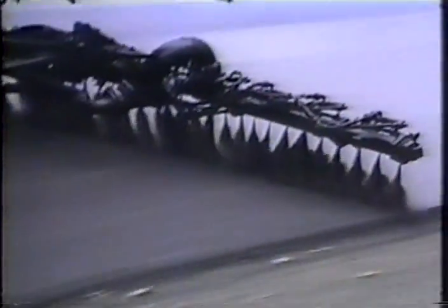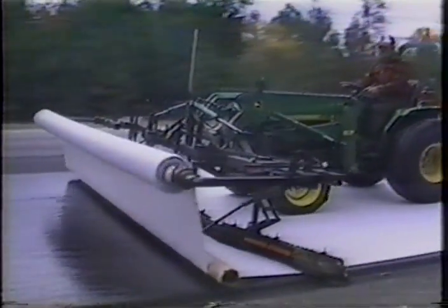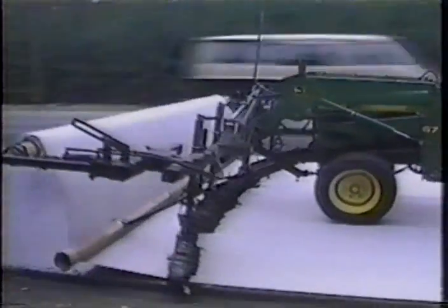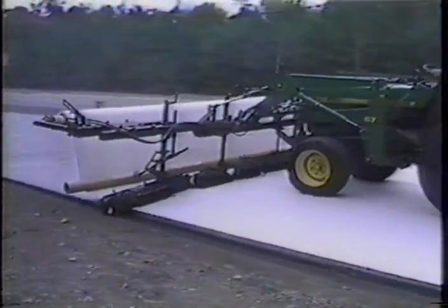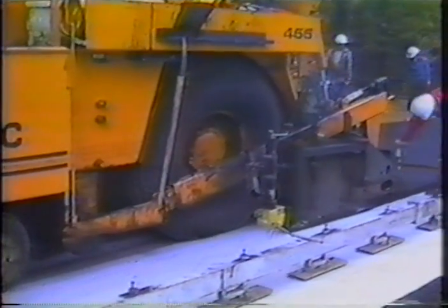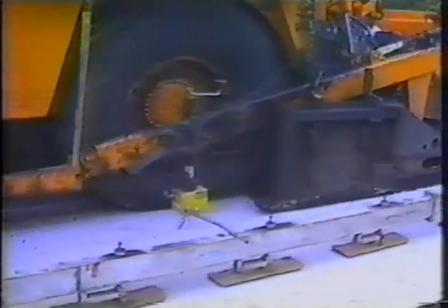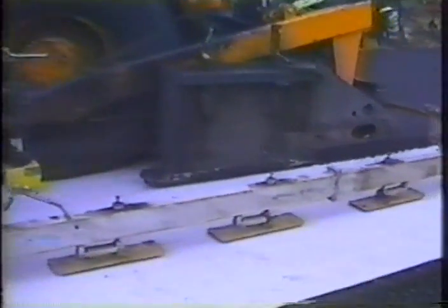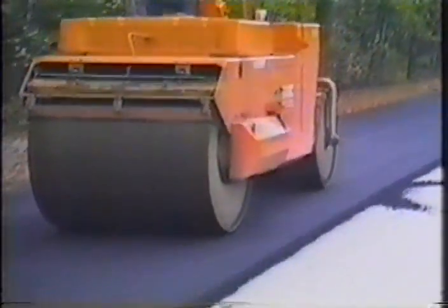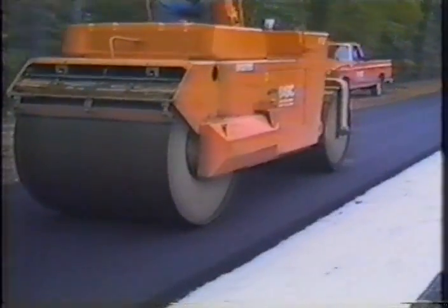An asphaltic material is sprayed over the existing pavement, and the non-woven geotextile is laid before the asphalt has cooled and lost tackiness. The hot mix overlay is then placed directly on the geotextile, saturating the material to provide a waterproof barrier layer. It's then rolled while the asphalt is still hot to compact the overlay.